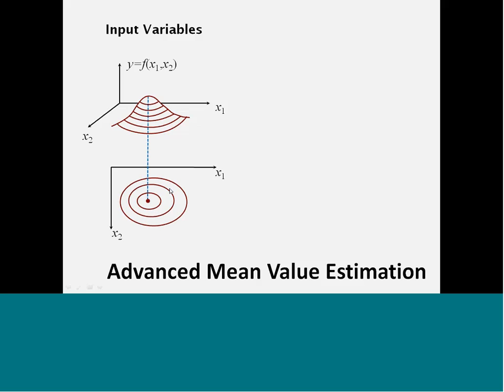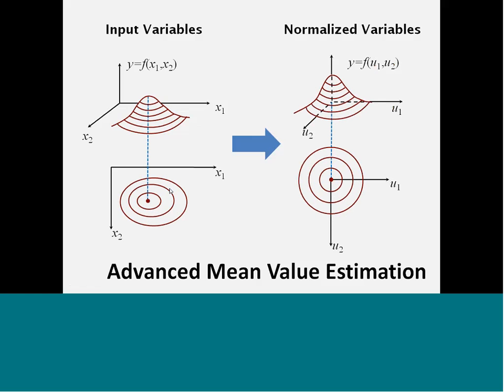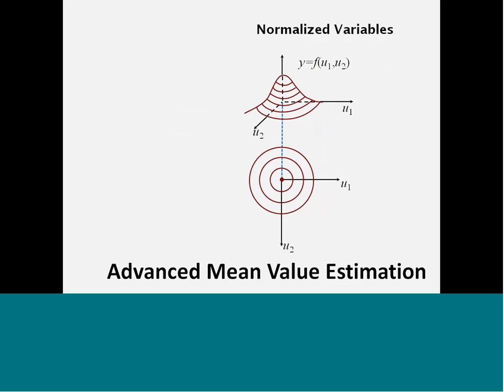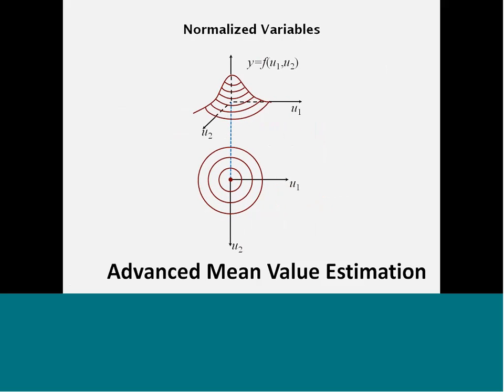The steps to do this are that we normalize the variables using a z-distribution, which puts the mean right at 0. After that, we approximate our percentiles, whether it's our 5th percentile, 90th percentile, or 60th percentile, it doesn't matter, using what we call the limit state function. And this is simply the desired percentile that we're after.